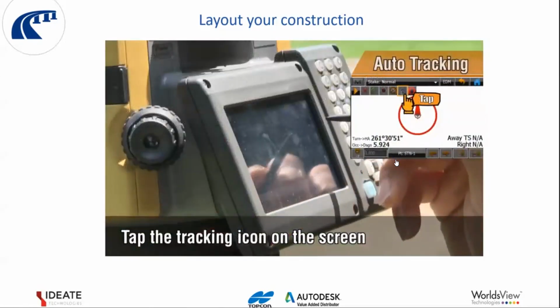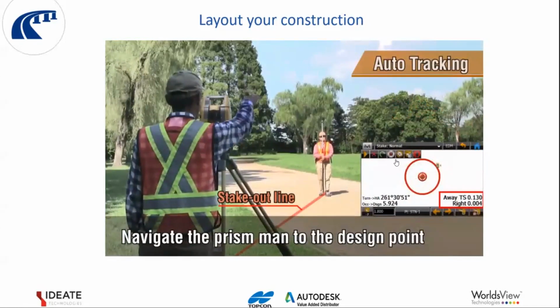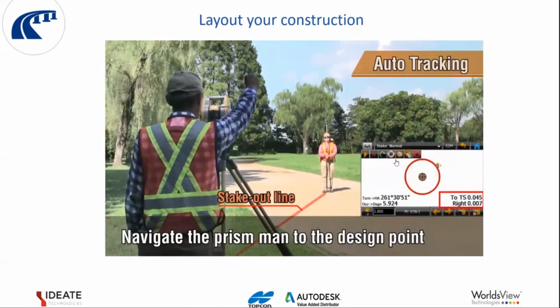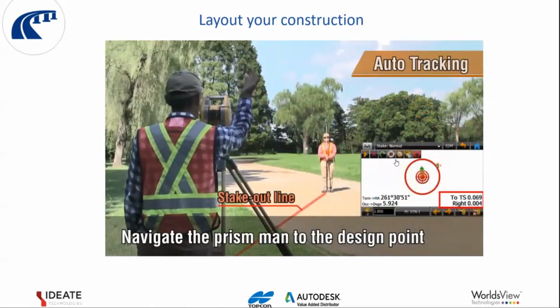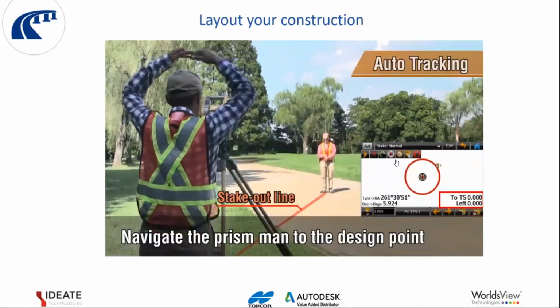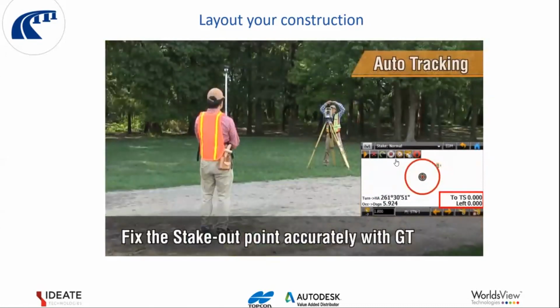In here, you keep navigating the prism man to the design point, and once he is on the right position, you give him instruction to stop and to stick that point.